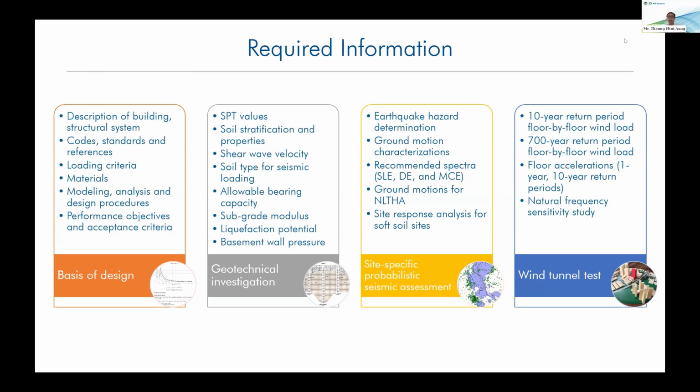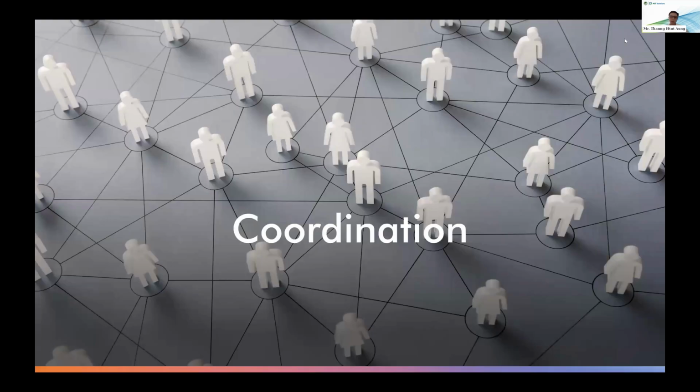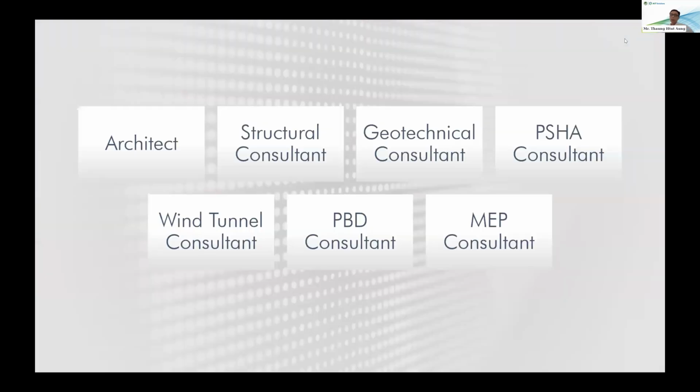They also conduct a natural frequency sensitivity study for their wind loads because our finite element models are not exactly the same as the actual building response. When we measure the natural frequency of buildings that are already constructed, they are different from our finite element model. So to consider that effect, the wind tunnel consultant conducts the frequency sensitivity analysis.